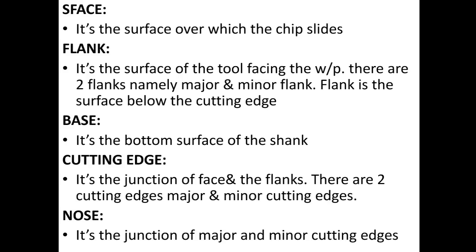Cutting edge, it is the junction of the face and the flanks. There are two cutting edges, major and minor cutting edges. Nose, it is the junction of the major and minor cutting edges.